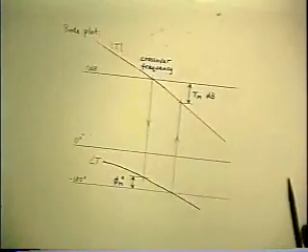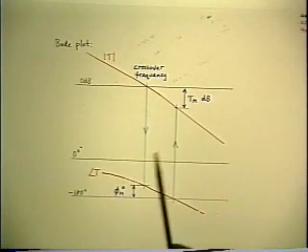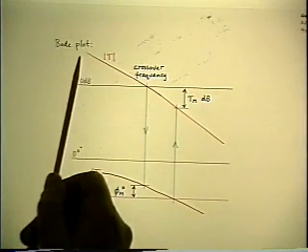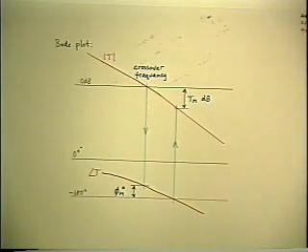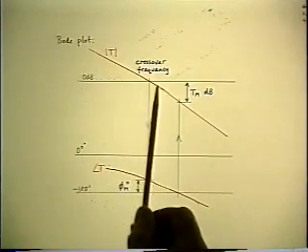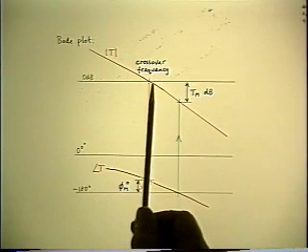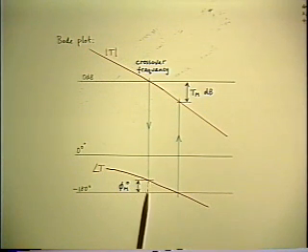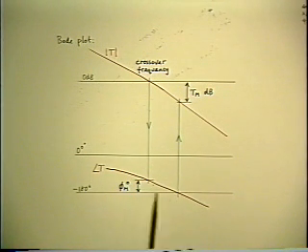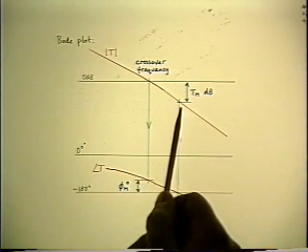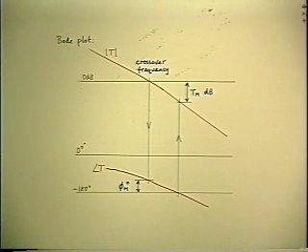And here's the same thing on the more conventional Bode plot, which is the plots we've been using all the time, which is separate graphs of magnitude and phase versus frequency. So here's the identification of those margins on this picture. You find the crossover frequency, which is where the magnitude is 1, and you look down to the phase graph, and how many degrees less than 180 it is the phase margin. And then you find the frequency higher up where the phase may get to 180, and you look back at the magnitude graph, and how many dB below 0 it is the gain margin.